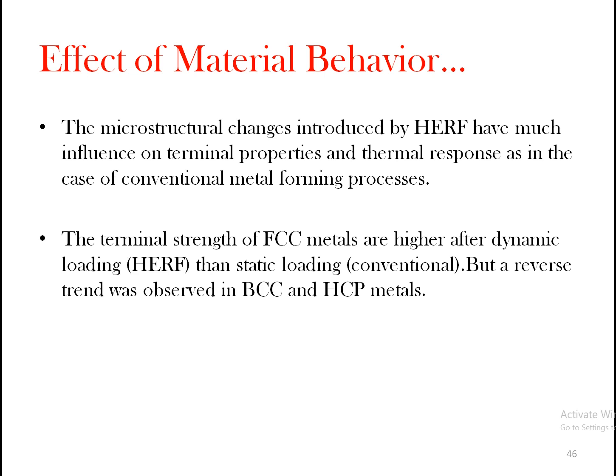The terminal strength of FCC metal is found to be higher after dynamic loading than static loading, but a reverse trend is observed in BCC and HCP metals, right? You might know what an FCC metal is. That means for high velocity forming, the terminal strength, that is the final strength, of FCC metal is found to be higher when compared with the conventional forming methods.